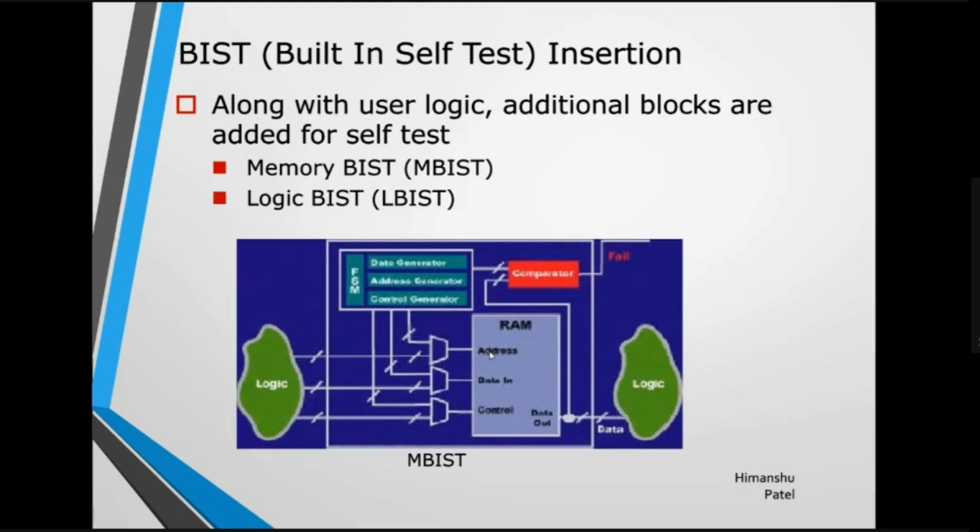But before manufacturing, when you're designing it, as a DFT engineer you have to make sure that each and every cell is accessible for read and write, and not stuck at a single value, either grounded or connected to VCC or VDD. The value of that cell should be changeable. If it is not changing, then it's redundant or has an issue. You have to identify it and fix it.